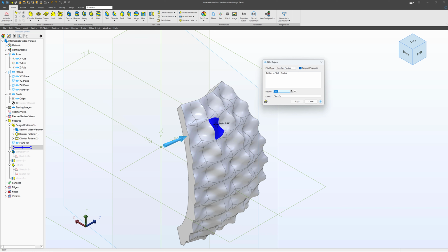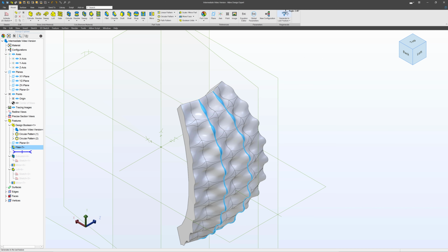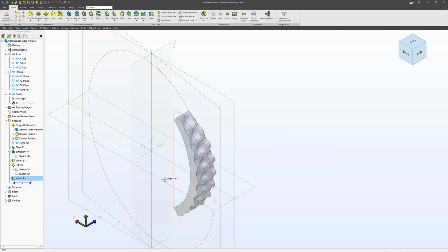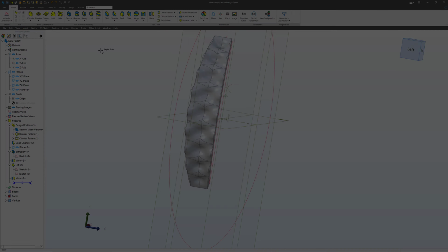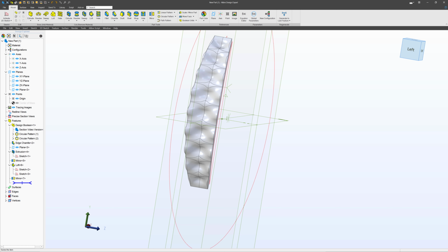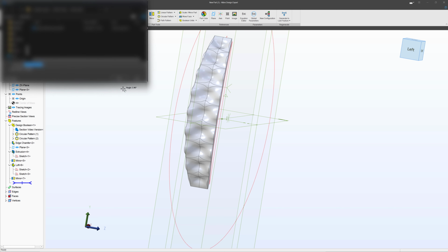And instead we'll replace this with a fillet. That might be a bit steep. Let's try 0.125. And we'll do the other side as well. Okay, now we should be ready to move on. So we'll generate to last feature, nothing broke, and then we'll save and close and go into our next part model. So I'm going to go ahead and save this as an intermediate to the final vase.